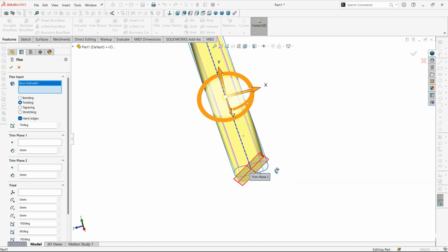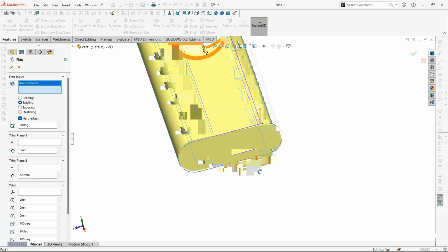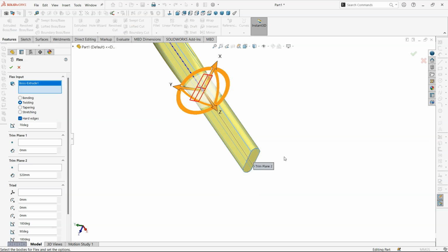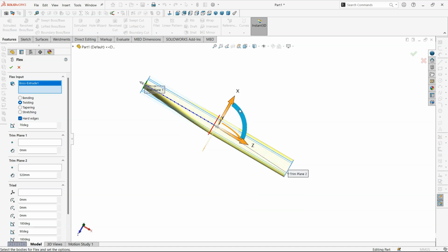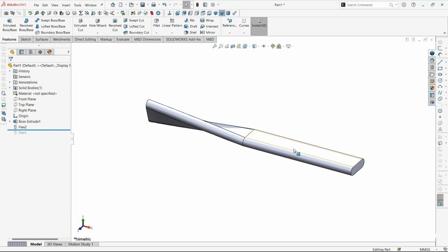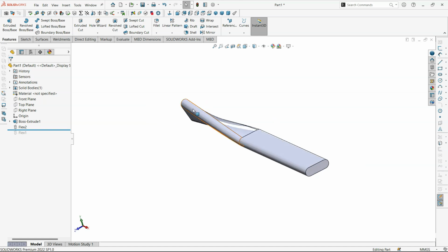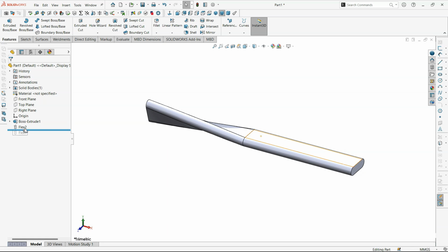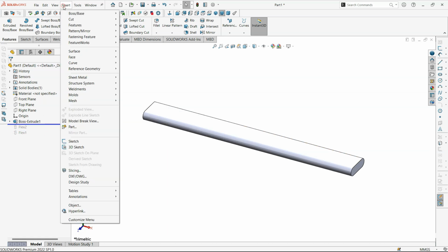Okay, now we can also change the direction of the plane from there. If we change the plane direction, the end becomes close to the original sketch. So that's how we can use the flex feature in twisting. I have moved the plane towards this, then this surface below the plane is now stable, is now straight, and the twisting starts next. So that's how the flex feature can be used here.